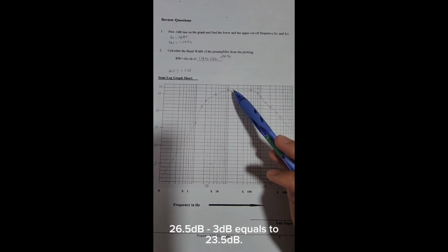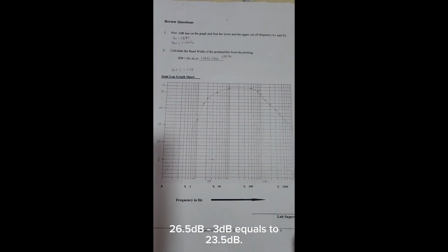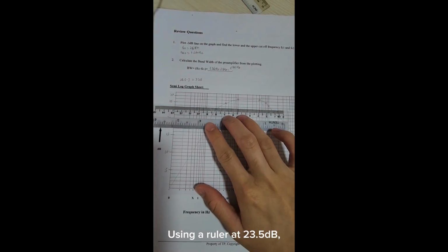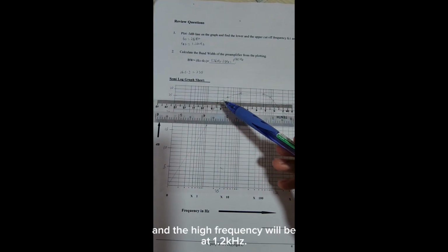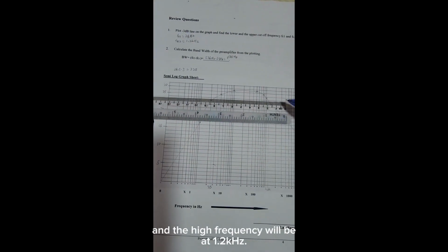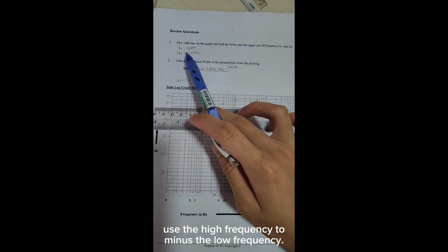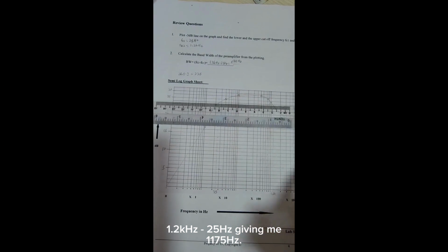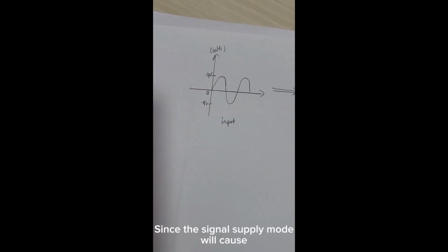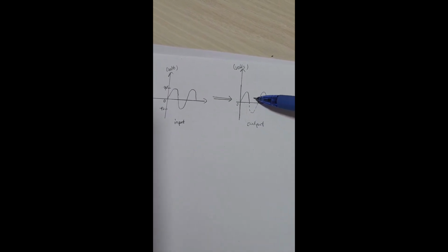On the frequency response curve, the minus 3 decibel line would be 26.5 decibel minus 3 decibel equals 23.5 decibel. Using a ruler at 23.5 decibel, the low frequency will be at 25 Hz, and the high frequency will be at 1.2 kHz. To find the bandwidth, use the high frequency minus the low frequency, 1.2 kHz minus 25 Hz, giving me 1175 Hz.